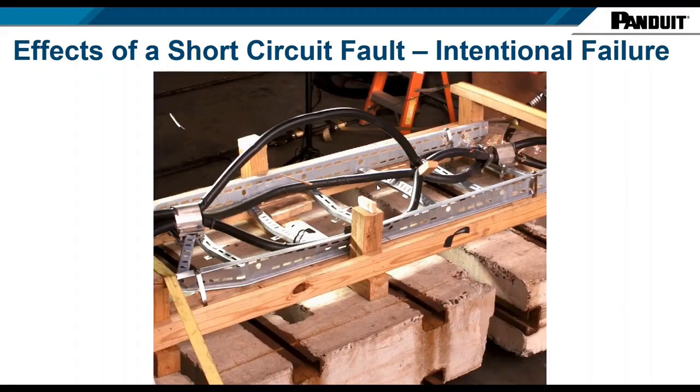And anything above this ladder would also be taken out because of that top conductor. You can see the amount of force has pulled in the end conditions of the ladder. And you can imagine this is only a rig of maybe 3 meters long. If you've got a 50 or 100 meter run, the damage has been limited here by the length of the rig. You wouldn't have that on site. The damage would be much higher.